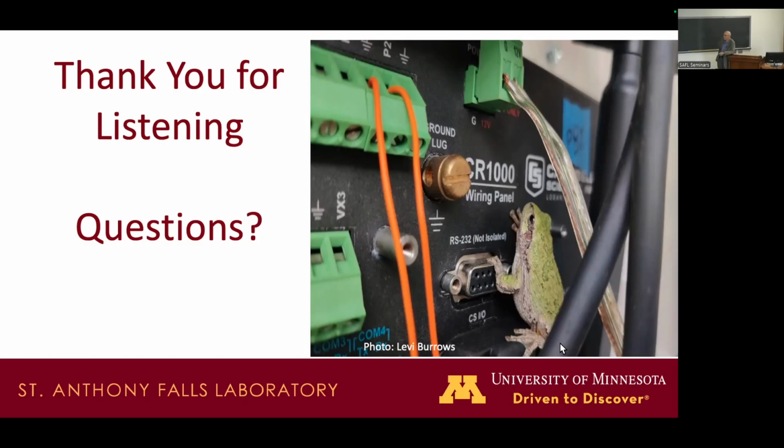Well, my answer to that, we haven't done really good analysis of cost efficiency, but an iron-enhanced sand filter is not going after the low-hanging fruit. So you need to get rid of everything else through settling, that's really the easiest way of doing it. A pond works really well to remove your phosphate because basically you're growing algae in the pond and hopefully settling those algae out. Then you have less phosphate leaving the pond than coming in, hopefully, if it's operating properly.